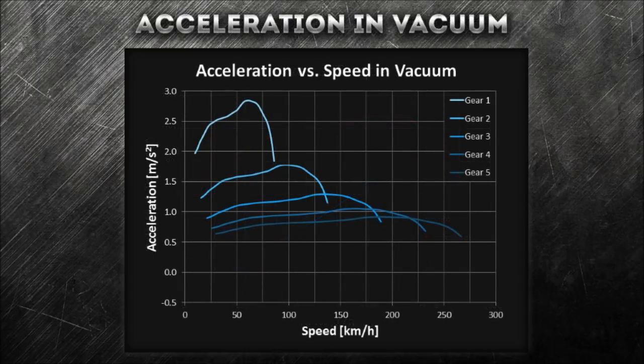In fact, every gear's acceleration curve is a compressed or stretched image of the original torque curve. Again, remember that this is because of the limitations that come with fixed gear ratios and not because torque is what accelerates a car. Let us complicate matters a little by making things more realistic.